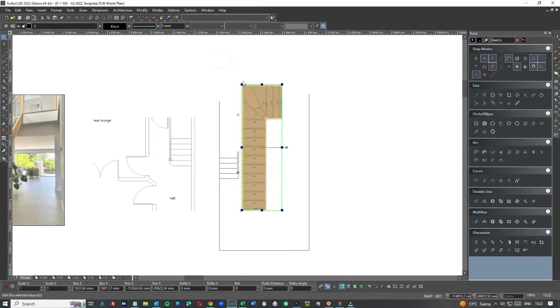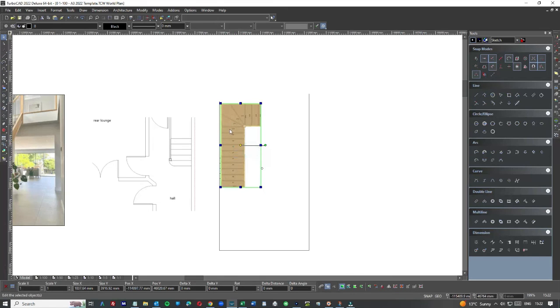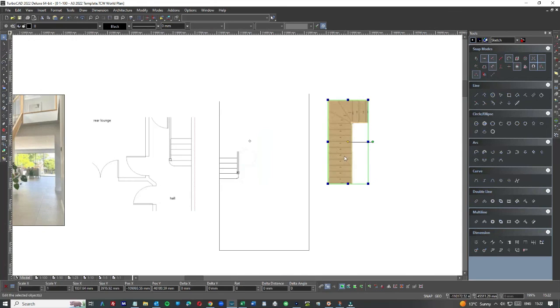But again, you can reduce these down, sit them into your drawings, and make sure, or what I normally do, if I'm doing a staircase, and it's not just cosmetic, I need to demonstrate the sizing of the staircase, is I'll go into a third party like Stairbox and actually create the staircase, and then I'll just do a cutout of it and pop it into the drawing beside the layout plans and make references to it. So that's really helpful then for whoever's got the drawing.